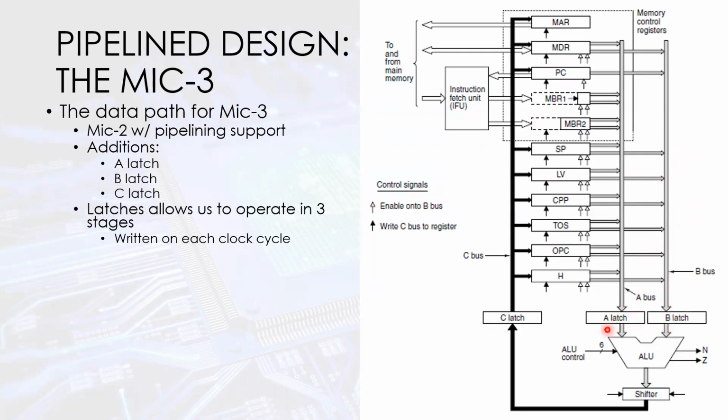But conceptually, what we see now is these latches allow us to operate in 3 distinct stages. So remember the sequential circuits, how we had the next state and the current state? When you made those circuits in the project, that was the key. Once you realize, okay, the output of the flip-flop, is that going to be the next or the current, based on the project?